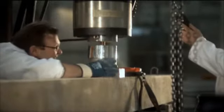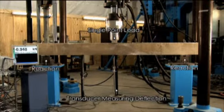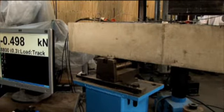The beam is loaded in 3-point bending. A single point load is applied at the centre of the beam, and 2 reaction points are supplied, one at each end of the beam. The supports consist of pivots which allow for rotation and translation at the ends of the beam.